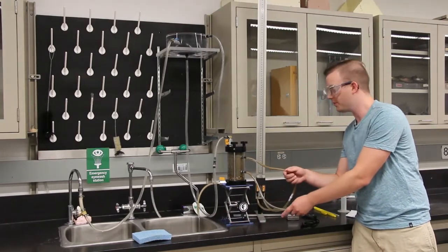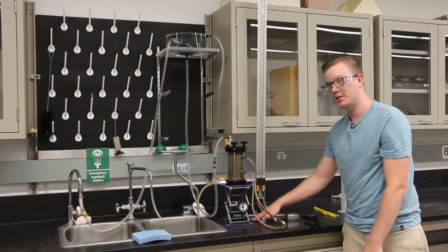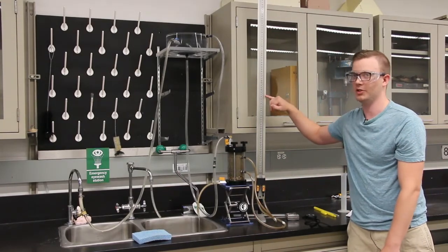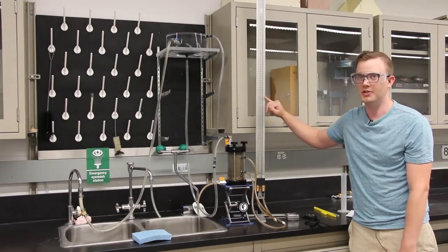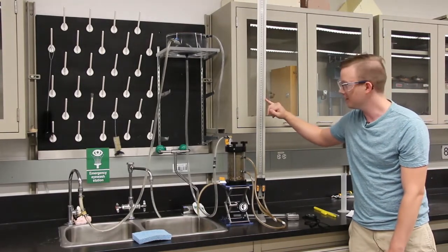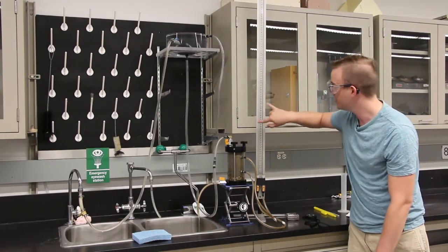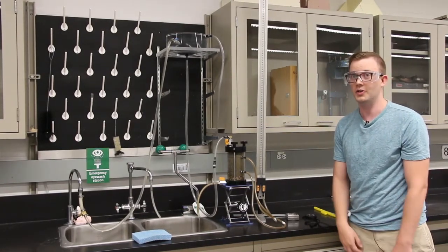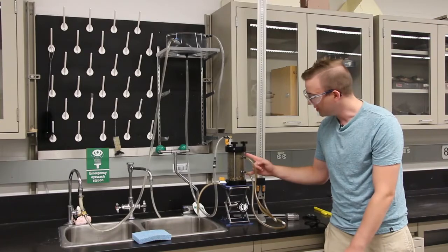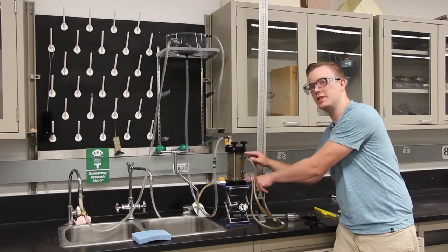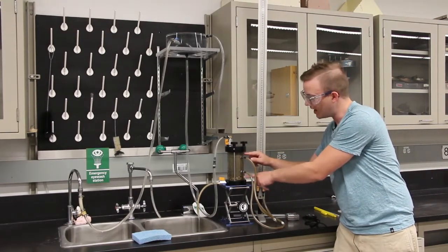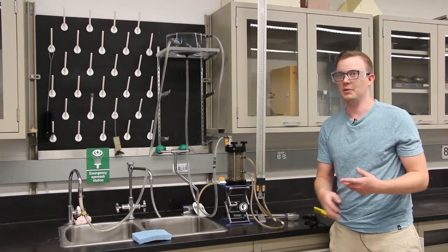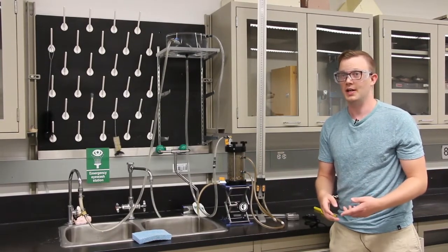of these two ports will be the distance from the table to wherever the water lines are in the respective manometers. Now, you really don't need to measure from the countertop in these cases because we can simply take the difference between these two manometers and you should be able to calculate your head difference at those two locations. You also want to measure the length of the sample and the distance between these two manometer ports. With all those measurements, you should be able to figure out what your hydraulic gradient is.